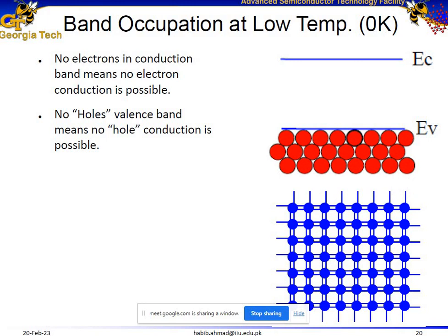Because we are going to study devices: PN junction diodes, Schottky diodes, LEDs, solar cells, and photodetectors. So we will talk about band gaps of different materials, especially silicon as the basic example. The band gap of silicon is 1.1 electron volts, which is the difference between the conduction band and valence band for silicon.